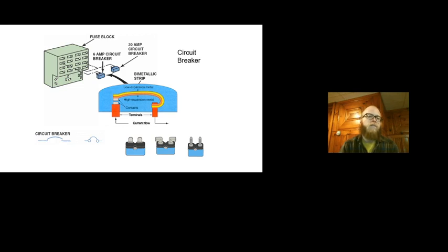Early blinkers were built to overamp a circuit breaker like this. And so the noise that you associate with a blinker, like click, click, tick, tock, whatever you want to consider it as, that device, or the circuit breaker under the dashboard, was actually physically making that noise. Now everything's gone electronic, and so people were so used to hearing that noise that now they have programmed it into instrument clusters to mimic that circuit breaker opening and closing and opening and closing, tick tock, tick tock.